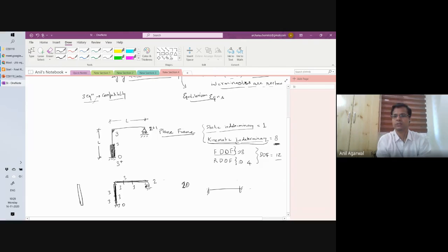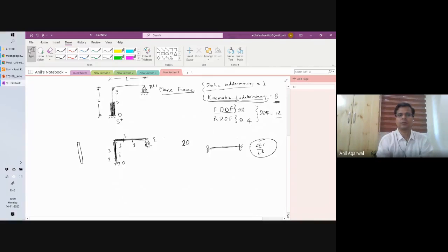When we derive the expression for a stiffness matrix, whether 6EI by L square or 12EI by L cube, all those expressions are derived for a straight member which has uniform EI value. Okay, no hinges, nothing in between. So that's how we define the kinematic indeterminacy. Everybody's on board, but still nothing stops us from defining more points of freedom or degrees of freedom along the way.